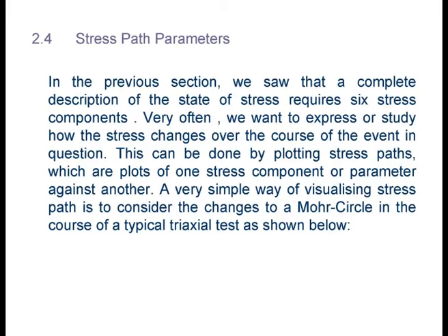Now, very often, because in FEM you're looking at simulation, you want to see how the thing changes during some event. The event could be excavating a tunnel, or excavating the soil, or loading a pile foundation. Essentially, you want to see how the stress changes over the course of an event, and that event could be an excavation sequence or a loading sequence. This can be done by plotting stress path.